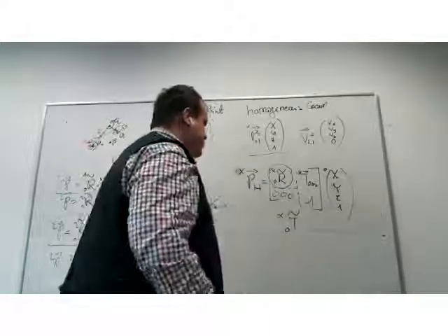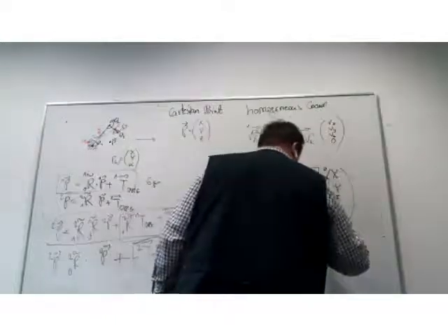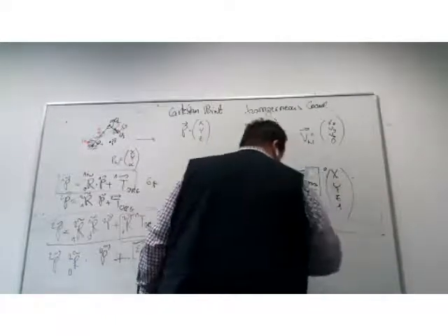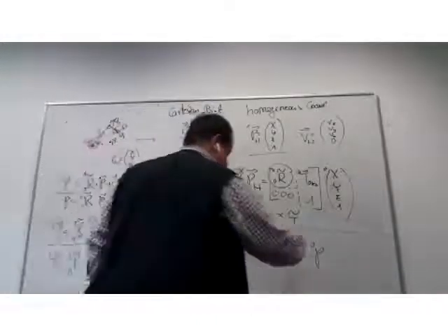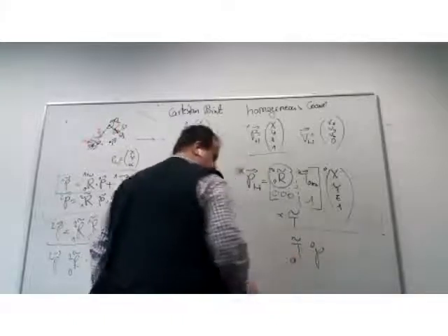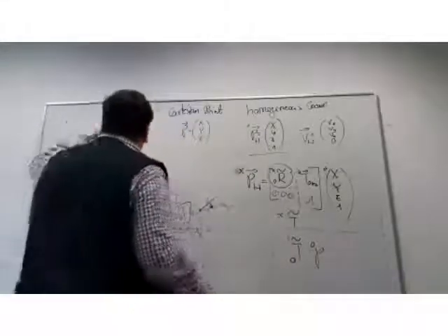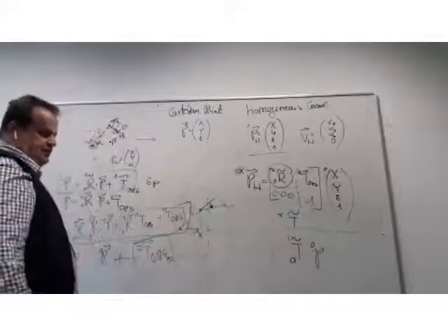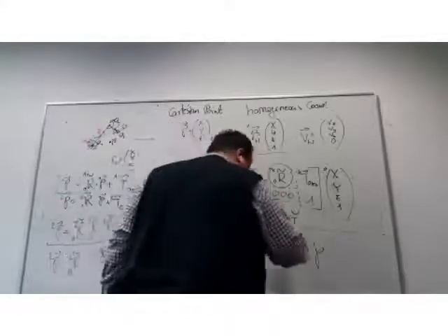One nice thing is that now, to transform my world point to the plane of the first joint, all I need to do is multiply it with the transformation matrix transforming from the world to the first plane. This gives me the representation of the point in the first plane. Do I want the representation in the second plane?